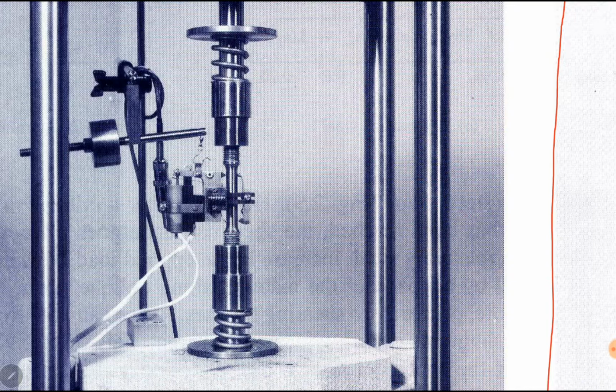The link AB is made of aluminum, so aluminum is not rigid. It is a deformable material. Value of E for aluminum is 70 gigapascal. It has a cross-sectional area of 500 millimeters square. So area for AB is also given. Link CD is made of steel. Value of E for steel is 200 gigapascals. And cross-sectional area of steel bar CD is also given, 600 millimeter square.